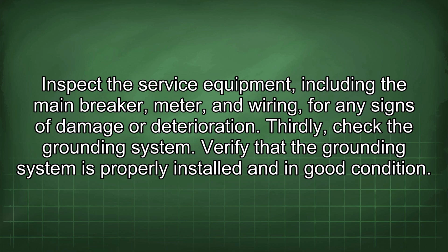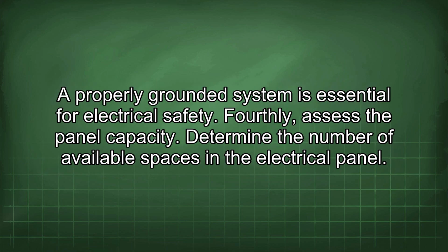Thirdly, check the grounding system. Verify that the grounding system is properly installed and in good condition. A properly grounded system is essential for electrical safety.